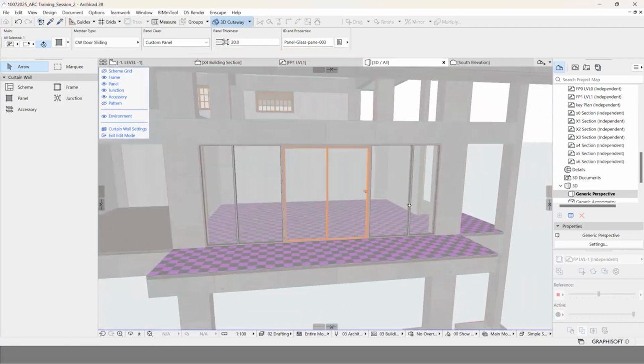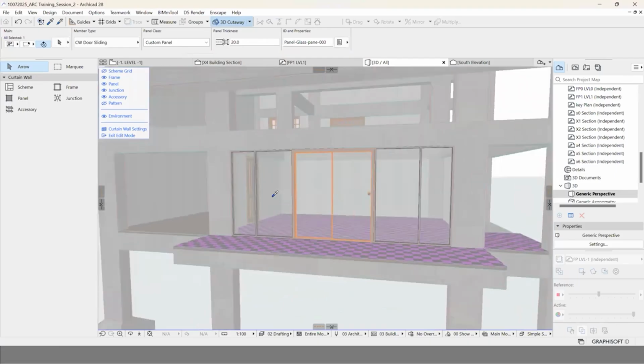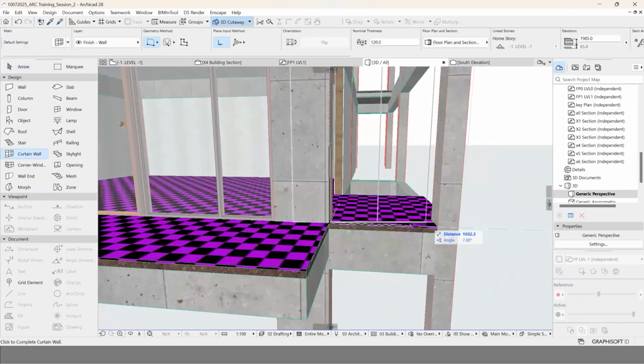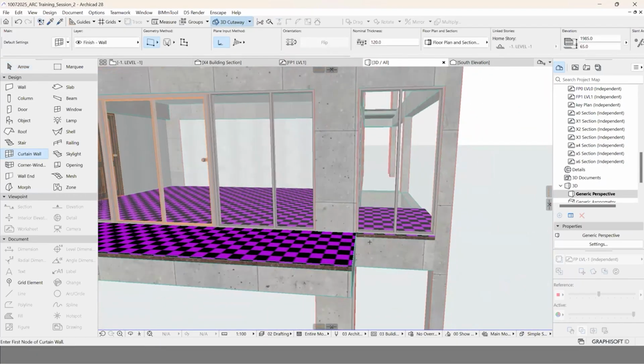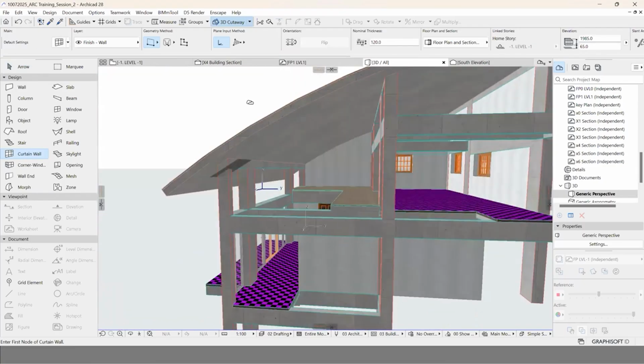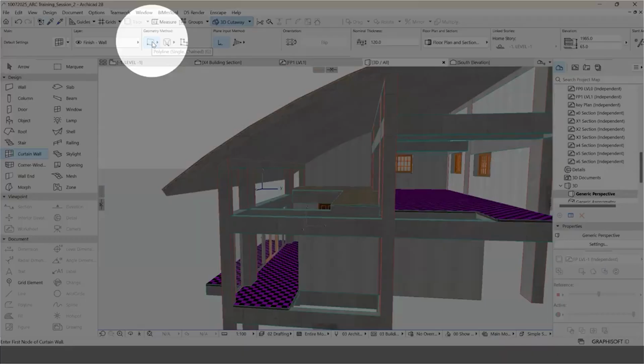Now, if I want something on the side, it is just picking the parameter of this, and I could just draft it even in 3D. So you can see it's already worked with the properties. Now, I was mentioning what happens when it comes to a complex shape. So in this, we are just going to change the drafting type. Instead of going for this chain method or line, what we are going to use here is a boundary method.